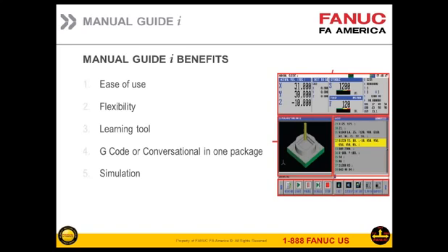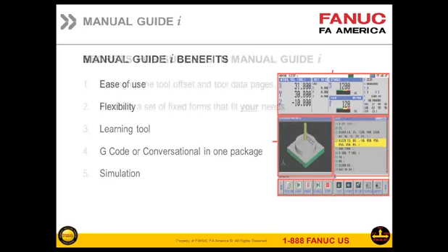And also simulation. You've got the capability of simulating both the conversational programs and a G-code program. As long as you have your tool data set up that matches with your CAM system software, you can simulate the program right within Manual Guide I.